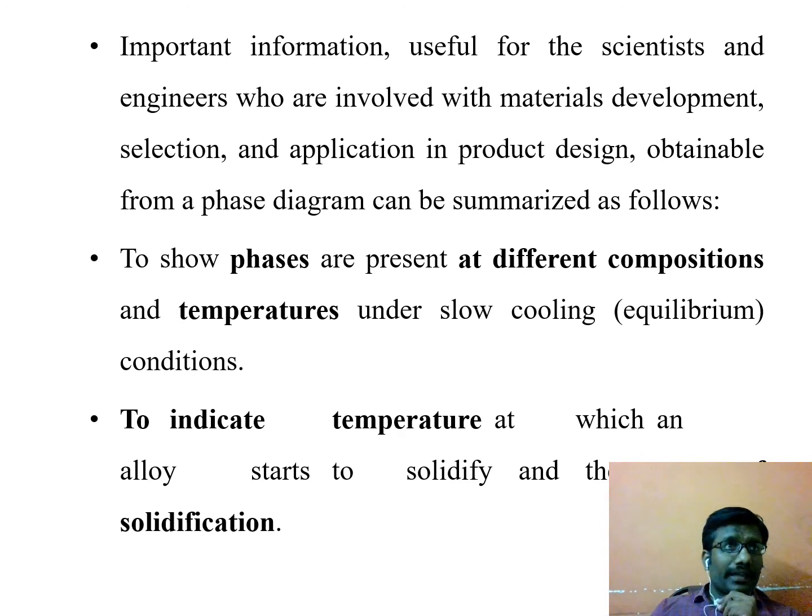At any temperature we can see the percentage of composition and what phase is existing, whether it is liquid, solid, or liquid plus solid. So you can identify this from the phase diagram.